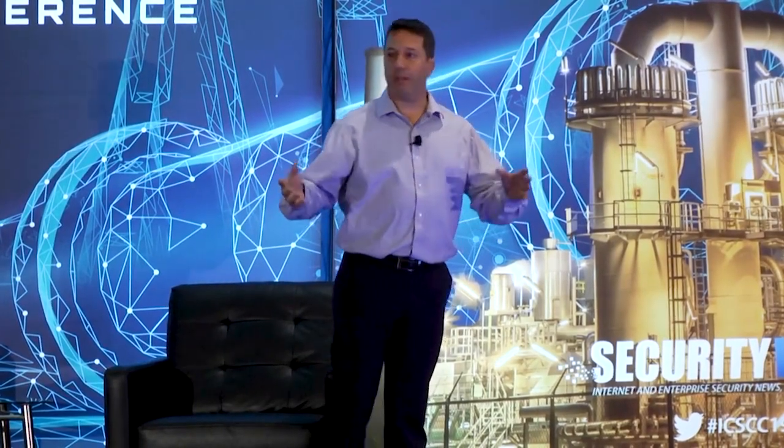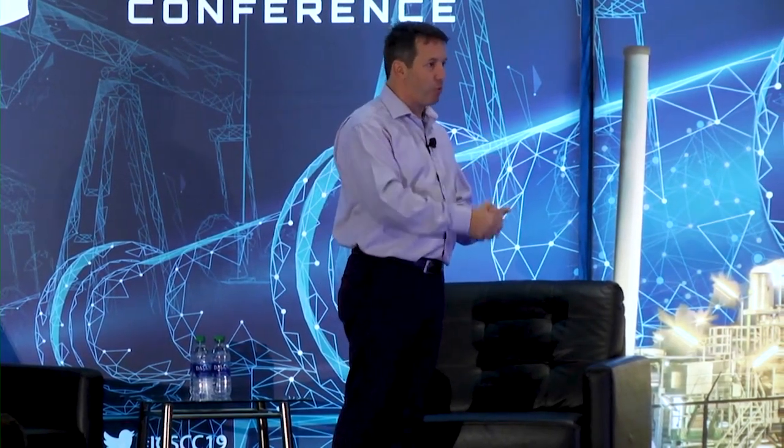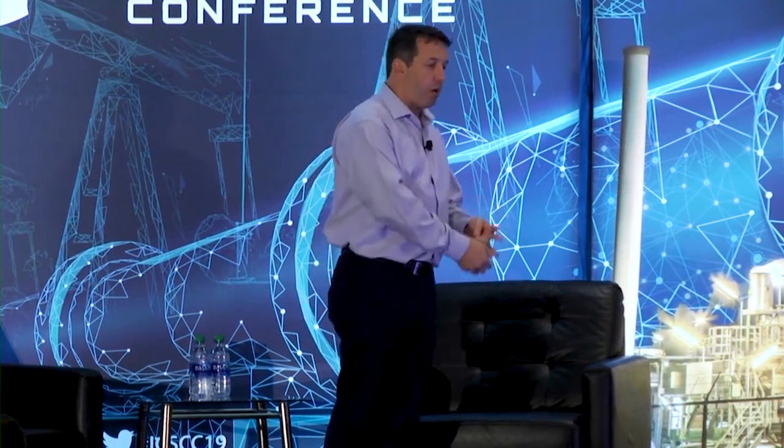Cloud-based stuff, and I'm probably going to get tomatoes thrown at me, but cloud-based stuff, I would actually stay away from, but that's my perspective. Take a little bit more of a conservative approach and lock the cabinets, make sure the screws are headless screws that nobody can actually take off, block all the ports, remove USB capabilities from any devices if you can, and have your security guard stand next to whichever supplier comes in to patch the devices. Unfortunately, nowadays, they will say, yeah, we'll guarantee our product if we can patch it remotely. In some systems, I'd rather pay more, buy a flight ticket and have the guy on site where I can keep an eye on that person.